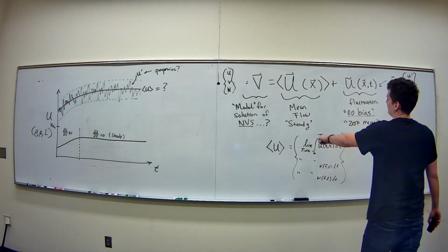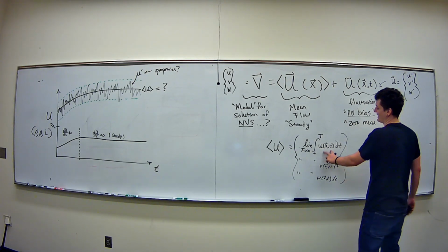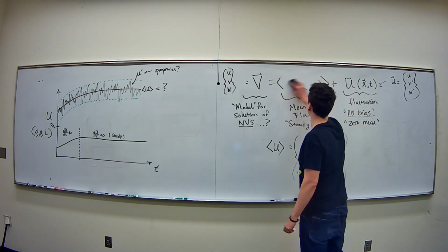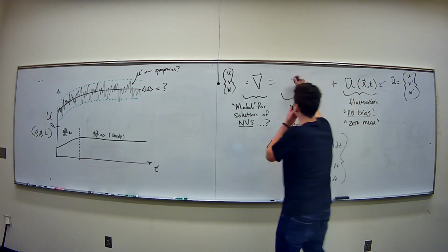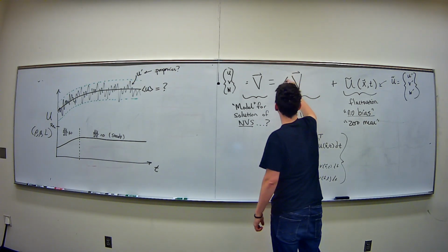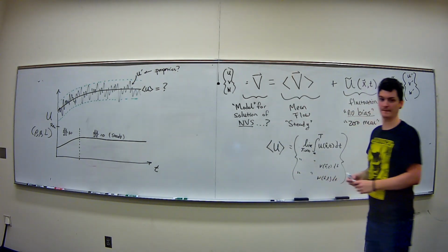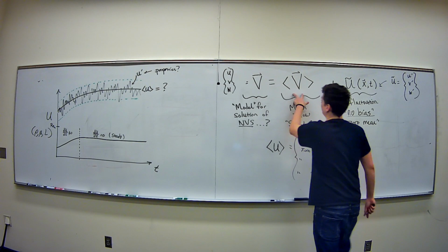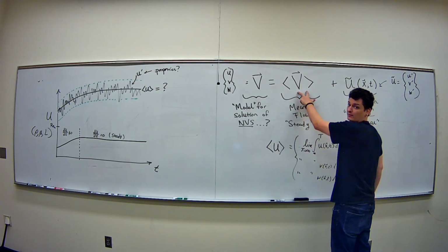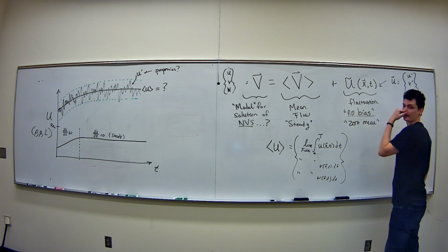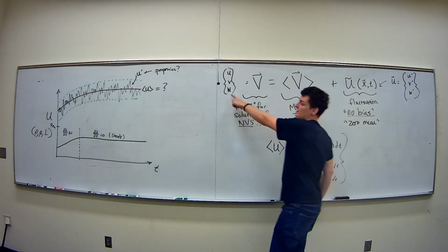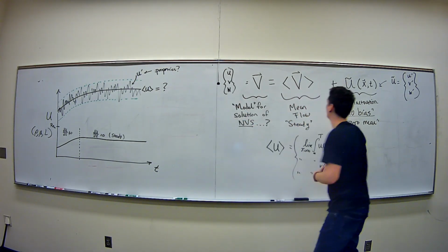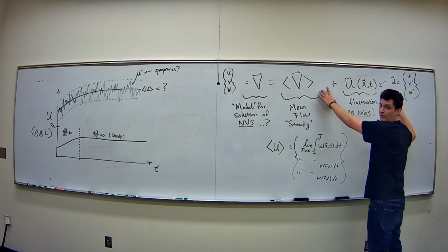Actually, in reality, because of this limiting or averaging I'm doing, I'm saying I'm taking the average of the solution itself, right? So that means your solution model is actually this. Solution meaning the solution of the Navier-Stokes equation will look like the time average mean of all the components plus some unknown part. So where before I had 3 unknowns in momentum, now you have 6 unknowns you'd be looking for.